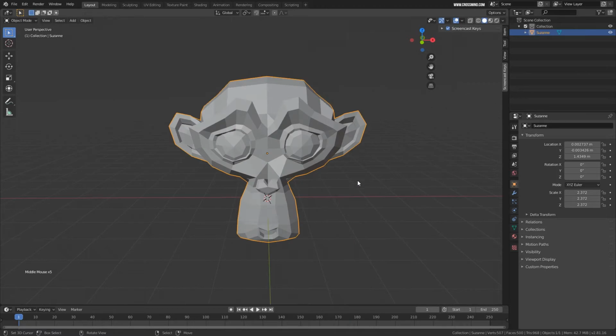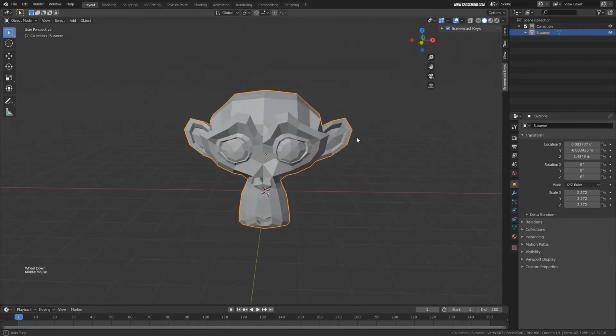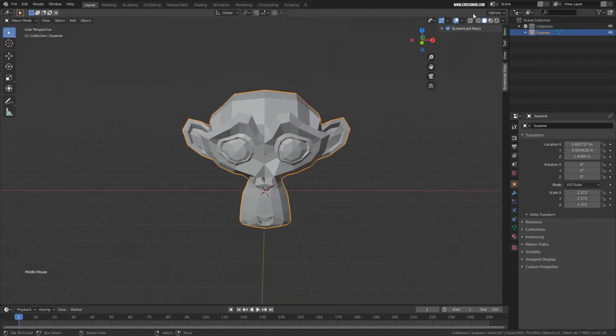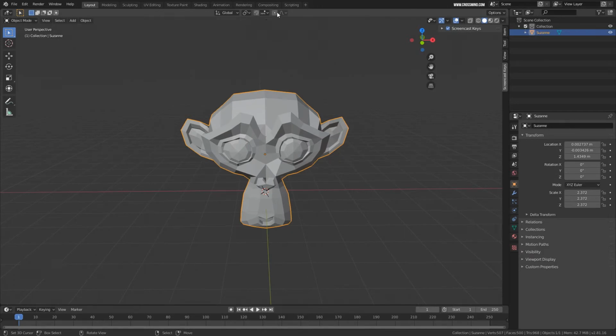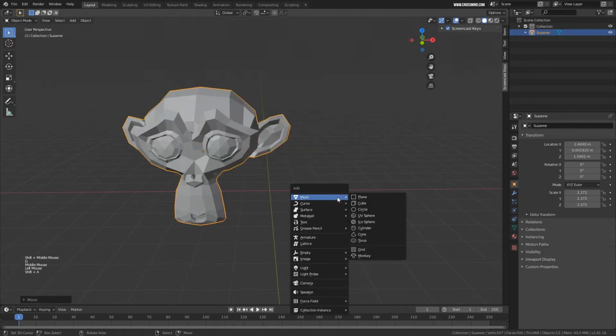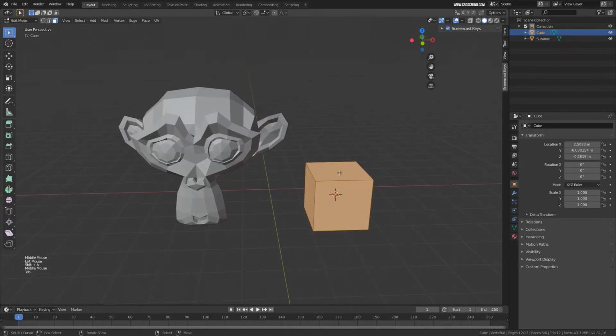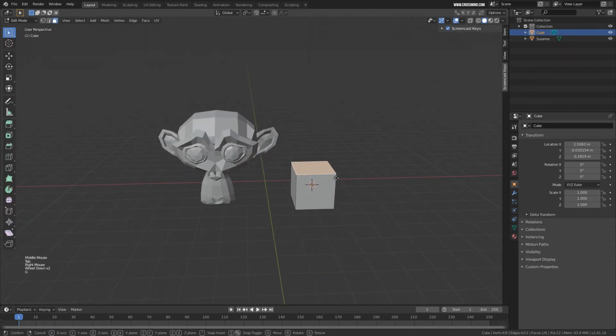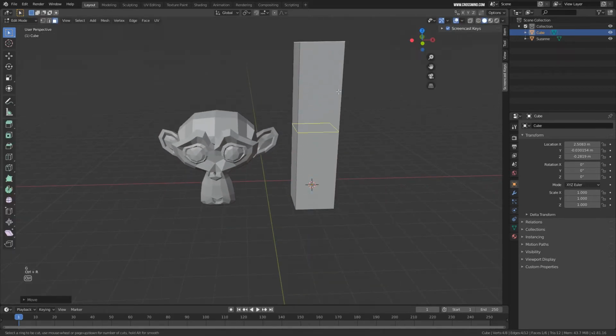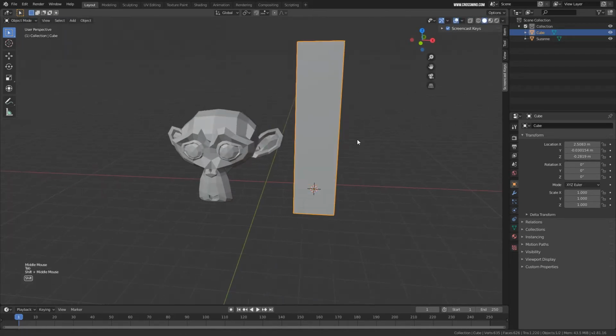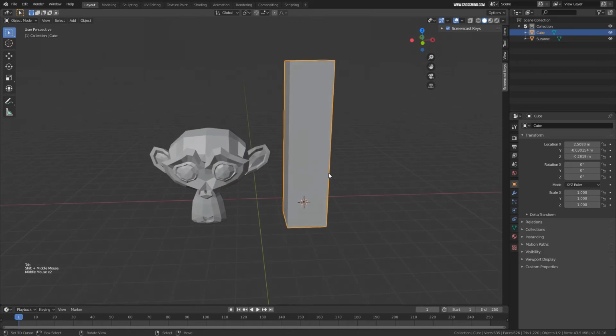All right, now let's talk about the most interesting one here, and this is called proportional editing. Okay, and in the first chapter, as we were discussing all these options, I mentioned this one we'll discuss in the next chapter when we are editing mesh objects. Now I think this is the right time we get into this one. So I'll just move this one and create a few loop cuts so that we can have some smooth mesh over here.